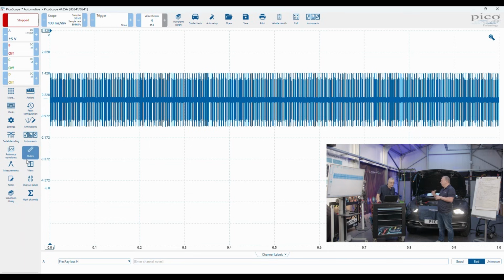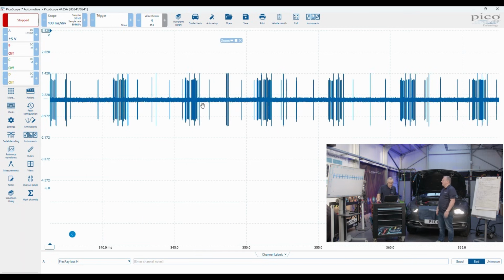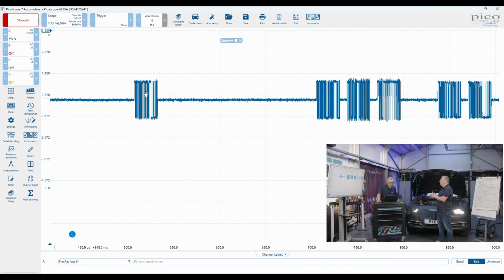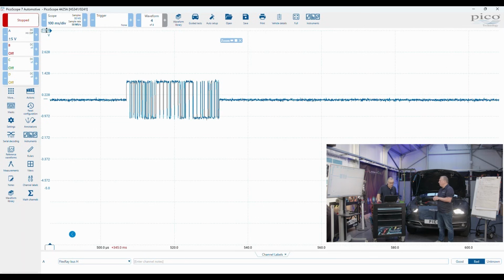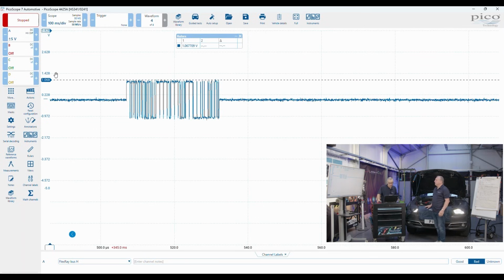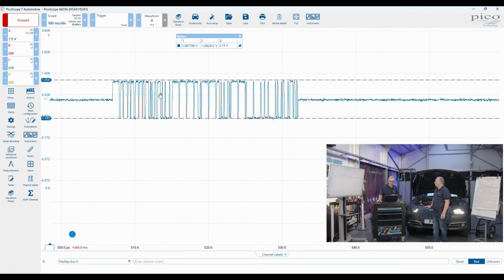What you need to understand is the difference in the measurement technique. What we're measuring now is the voltage difference on the bus. And if you understand how the network works and you use this measurement, you're very economic with your channel use. Which is all important when we're diagnosing, because with 3 more channels, we may want to analyse ignition or even use an accelerometer for undulation in the road. It may be that when you hit something in the road, the FlexRay goes offline or there's an event in FlexRay. Having the accelerometer on there means you would capture that event.